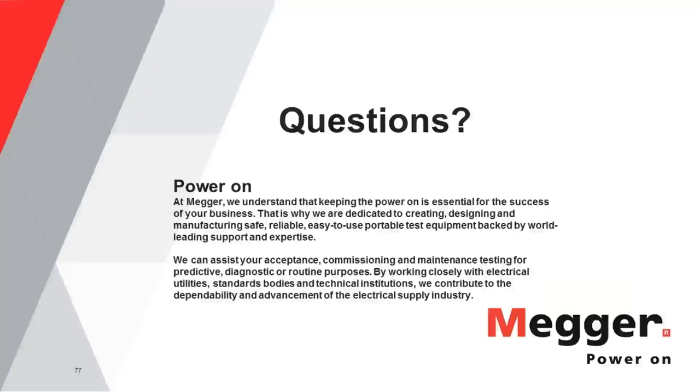I have another question for you, Jeff. IEEE 43 says that readings above 5 gigohms on a motor, generator, etc., are greatly affected by factors other than insulation resistance, and therefore PIs are not recommended as an assessment tool in this case. What are your thoughts on this?